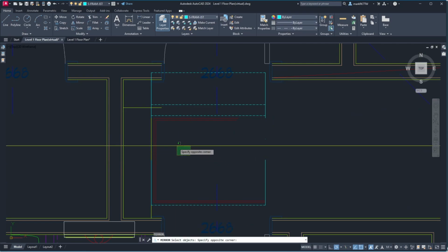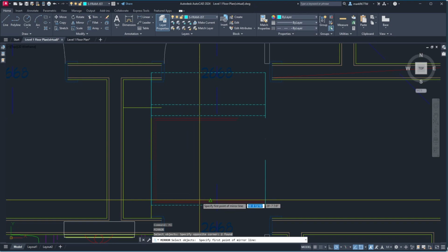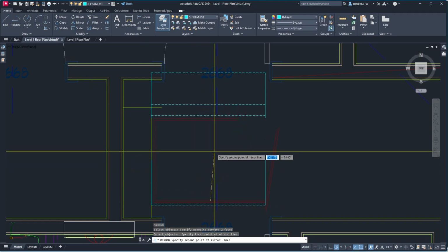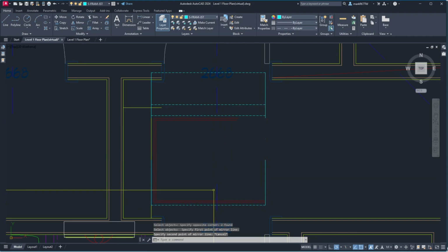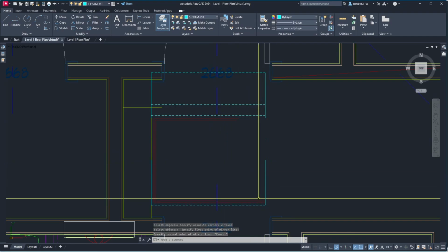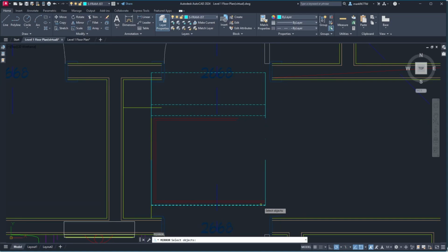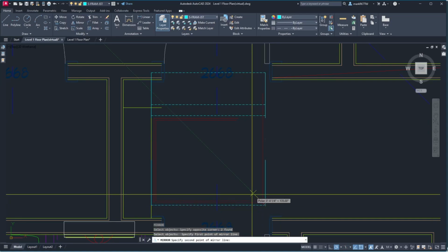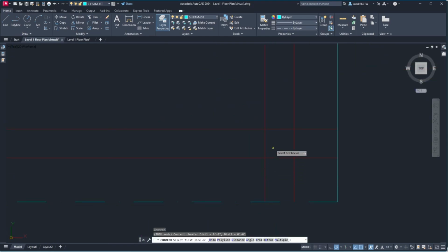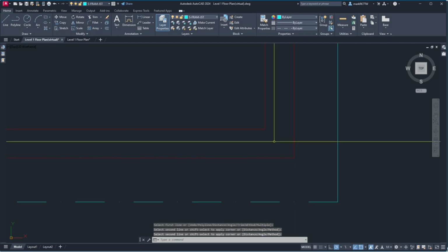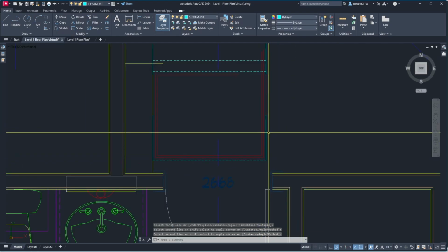If I mirror that about the midpoint of this guy, that certainly doesn't, oh, it's because this is coming all the way to the end. So I need to mirror these two off of this black corner to get it to come out to where it's supposed to be. So now I can chamfer and I'll have my opening complete. Then my measurements are to this line here.